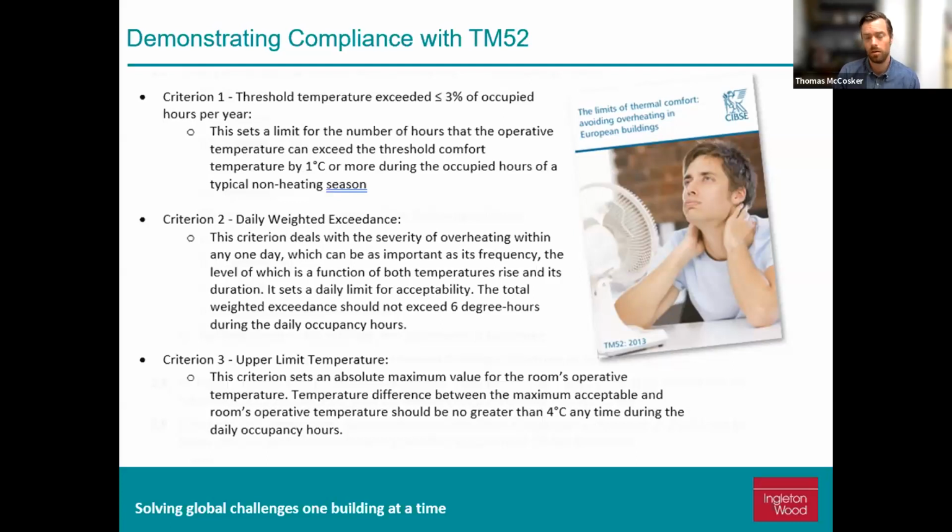All of these have to comply with the same regulations and design considerations that Jason mentioned earlier. That's going to be the security, the internal gains, the window opening degrees and everything else. So this is a logical step to do following a simple method, because all of those theoretically have already been set out by the design team. It's just a matter of putting them into a dynamic thermal model and bringing that into fruition through a number of hours of dedicated modeling. The TM52 is that second piece I was going to talk about, and it forms the background of TM59, which in turn forms the backbone of Part O.